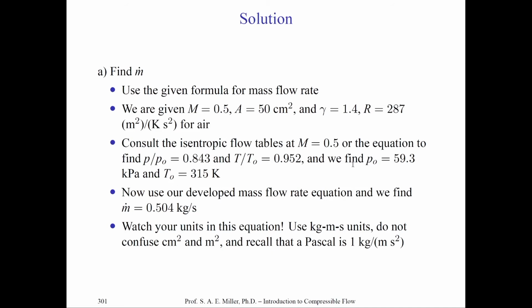and so that's a very valuable thing to know. Anytime you're doing an isentropic problem, I really recommend reaching out and finding P naught, T naught, and rho naught, because you know that they'll remain constant through your entire flow field as long as you don't violate the isentropic assumption. Remember what the isentropic assumptions are.